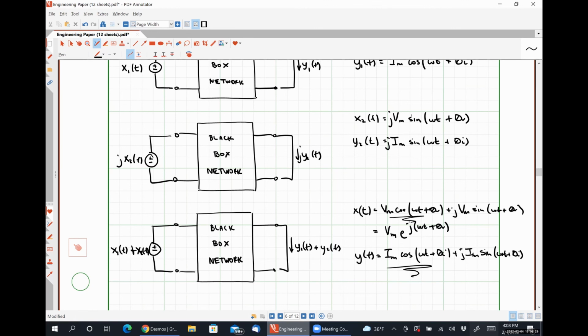So just relationships based on complex numbers, and find that we can absolutely avoid all of that terrifying trig and calculus that we did earlier. Working in the frequency domain turns all of our calculus into algebra, and we'll see that we can actually treat all of these sinusoidally excited circuits like DC circuits in the frequency domain.